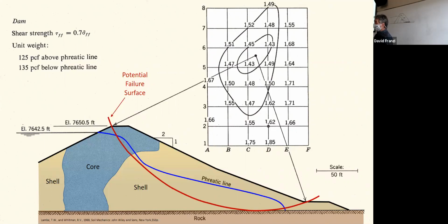Okay, so all these things are very carefully designed by engineers so that they don't do that. But yeah, you could theoretically. We'll be looking at slides of the Teton Dam disaster, and that was a case where the dam failed because they didn't put much core material in there. In fact, when the Army Corps went in after the dam failed and cut through the dam to expose the side and see what the heck happened there, it was very difficult to see that they used any really impermeable core material for the interior of that dam. And what happened was, if there's no core material,